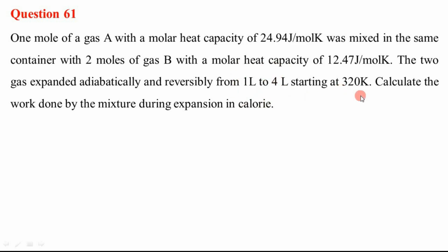Starting at this one, here we can calculate the T2, then calculate the work done by the mixture during expansion in calorie. Here they ask me to calculate the work done in calorie. We have reversible. So here, we need to make sure that we use the combined moles. That means the total mole will be equal to 2 plus 1 mole, which will be equal to 3 mole. Then we need to use the combined CV. The molar heat capacity, we need to combine them.